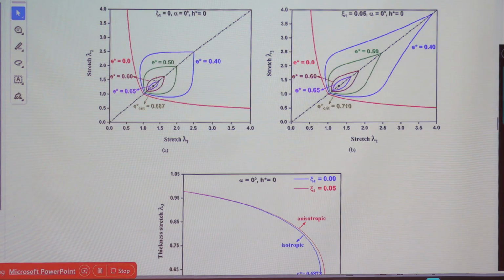Now if we are considering the wrinkle region, basically if we want to define a wrinkle-free region, or we are trying to develop a wrinkle-free region, this is a region in which no wrinkle will occur. Why? Because both the stresses are positive, so no compressive stress will be developed. So if we want to define a wrinkle-free or wrinkle-resistant region with the help of the tau domain, this is that region. Outside this, there is a possibility that wrinkles will form. You are getting my point?